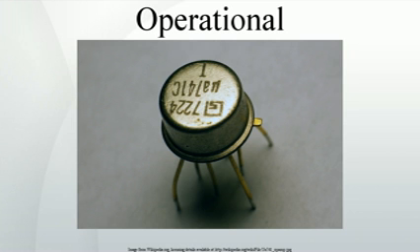The output sink transistor Q20 receives its base drive from the common collectors of Q15 and Q19. The level shifter Q16 provides base drive for the output source transistor Q14. Note the similarity between the transistors Q15 and Q7. The transistor Q22 prevents this stage from saturating by diverting the excessive Q15 base current. It acts as a Baker clamp.